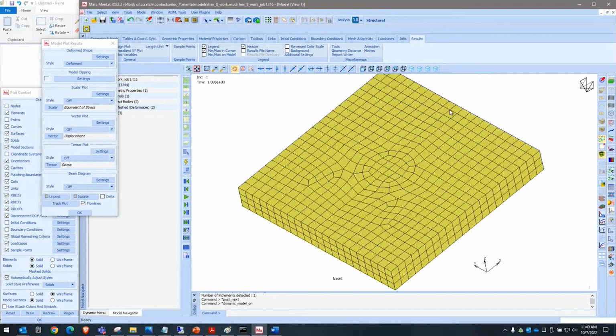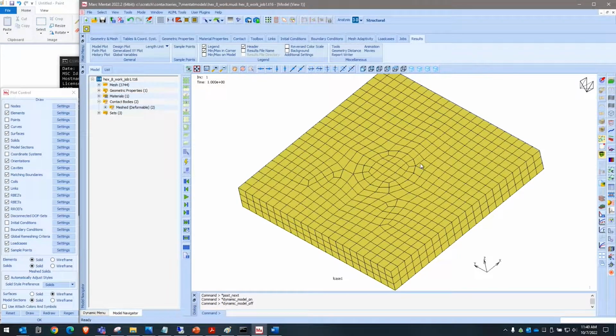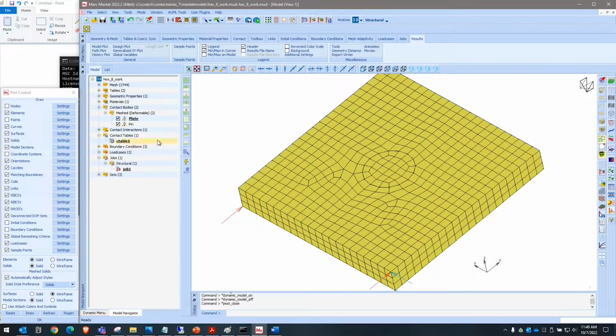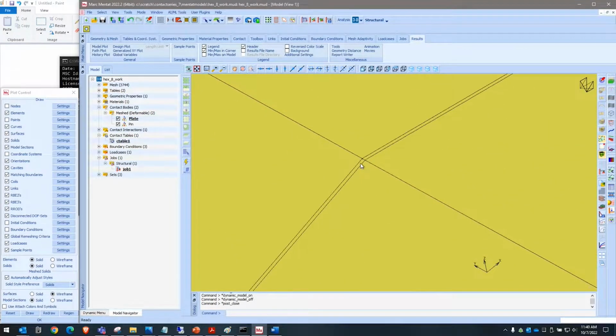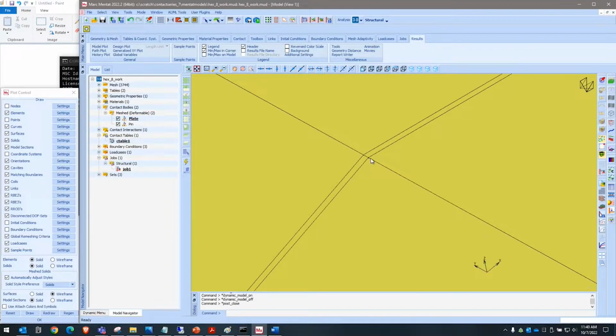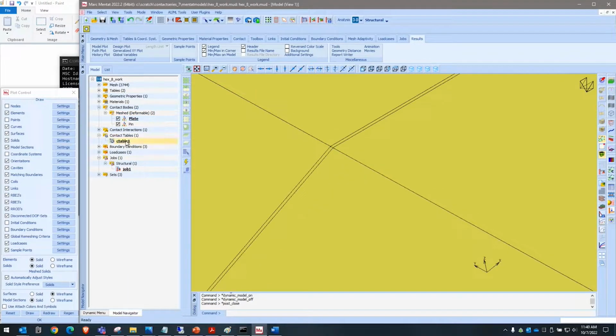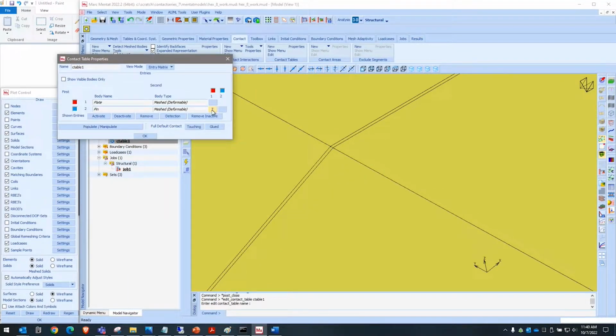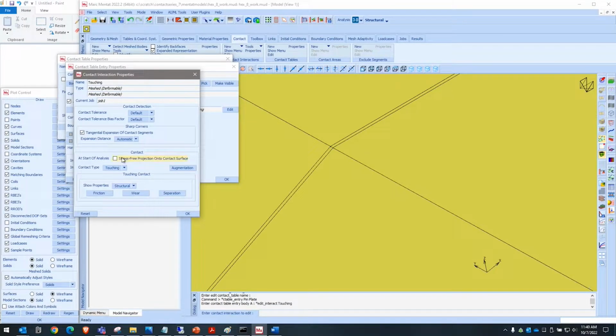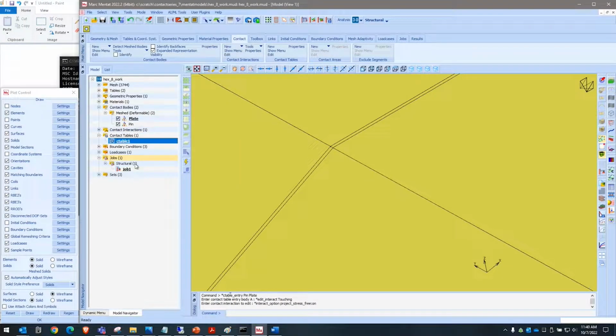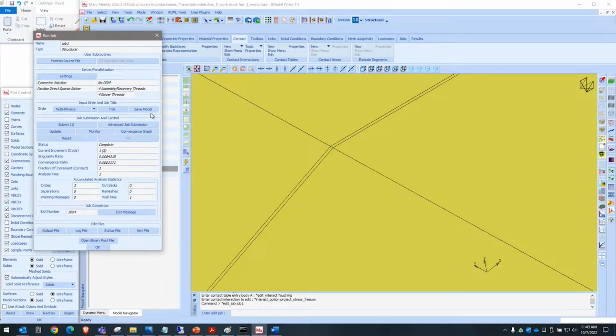Okay, so further improvements we can make, bear in mind we had that slight issue of slightly strange stress distribution initially. So let's say I want to use project stress free. That'll mean we'll move this node back to there, and that's not what I had in mind. So let's just see if I do this. Now, just to prove that that's the case. By project stress free, I should again see very close to zero stress, and the nodes will still tie up after the run.